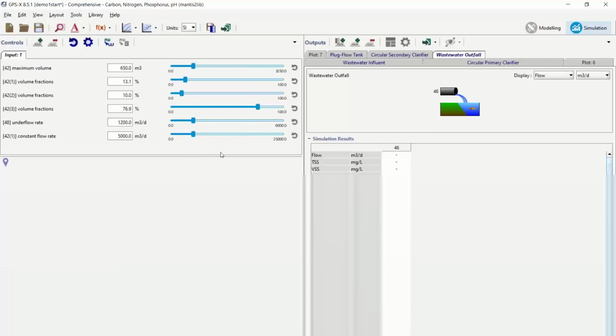And you can see that really actually did improve a lot. It went from 8 point something to 5 point something, right? So that's good. How's our ortho P? Well, it went up a little bit, but not too bad. No, sorry, that came down from 0.5 to 0.2. This is what went up, the ammonia, right? So ammonia is kind of creeping up a little bit. And of course, that makes sense. We've carved off some of the aerobic zone that was doing the nitrification. So that's cool.